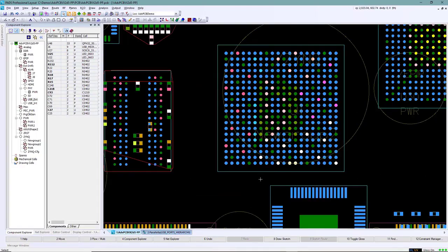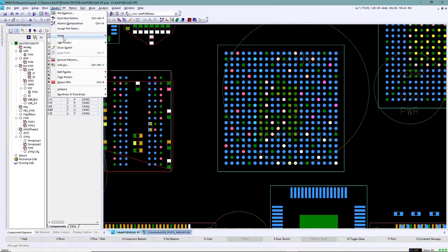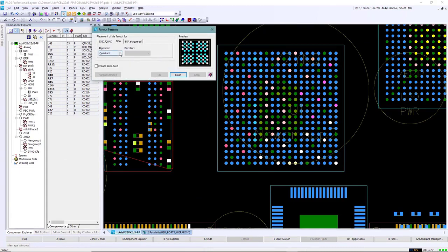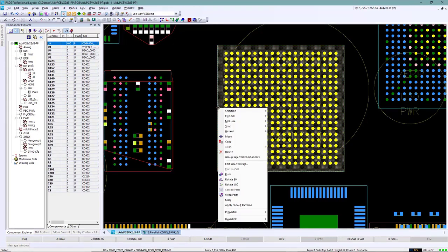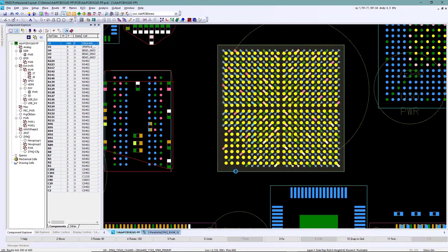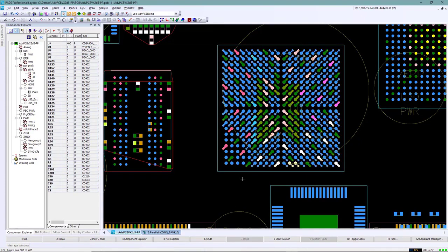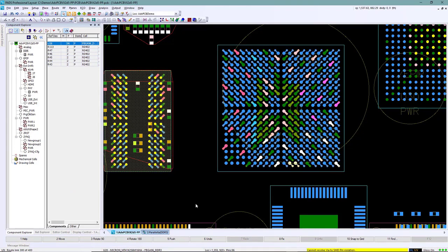One of the simplest forms of routing automation is fanning out pins from SMD devices, which is the process of using auto-routing technology to route short traces to a via so a net has access to internal layers. To take full advantage of automated fan-out, some rules will be required. Additionally, defining what direction traces will be routed is highly recommended.